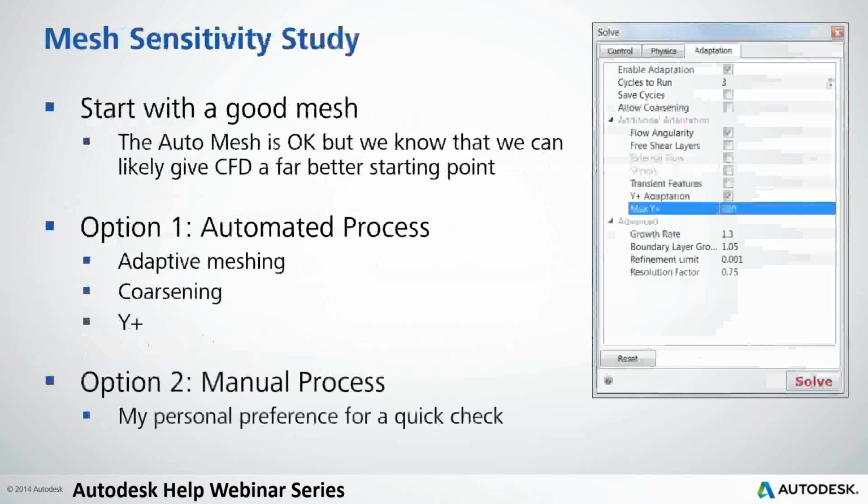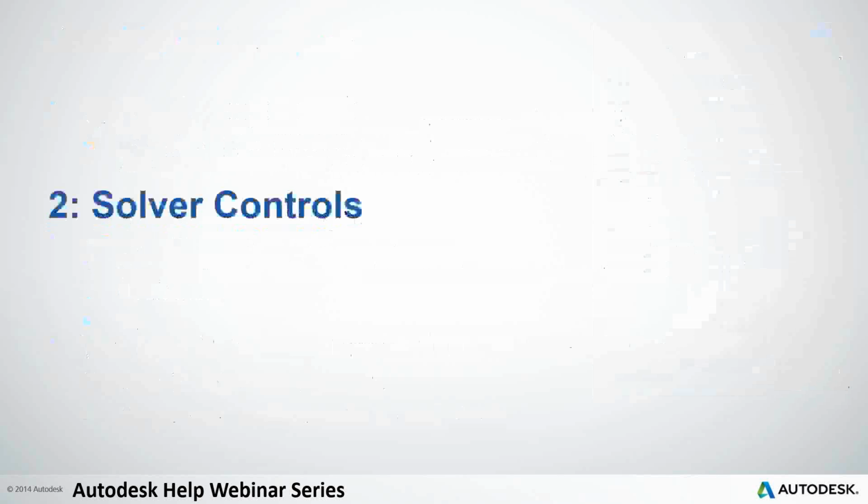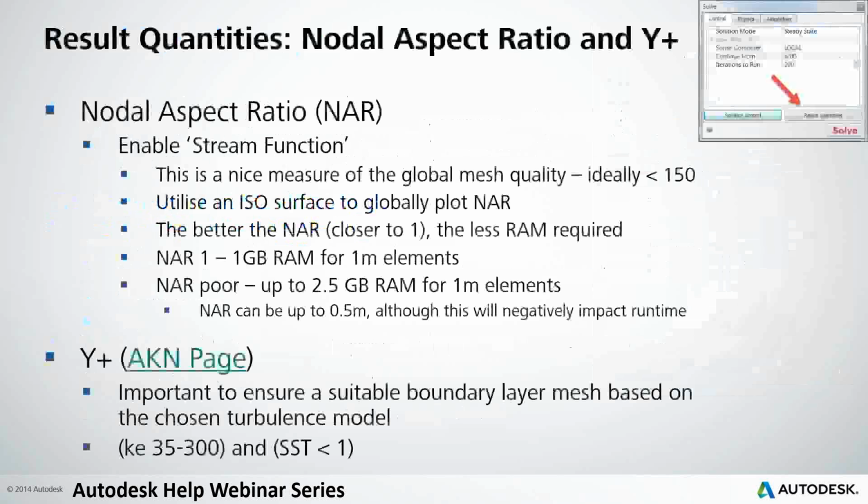But yeah, going back, within the box, yes, we can control the Y+ value, and this is a maximum value, and CFD is going to adapt to below that value. The reason why is as follows. I first want to explain how you turn it on and how you see what the Y+ is, but there's also another value that's important.